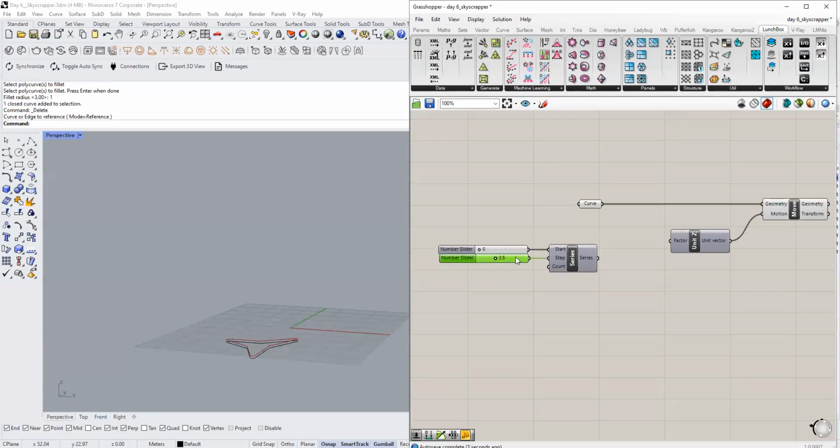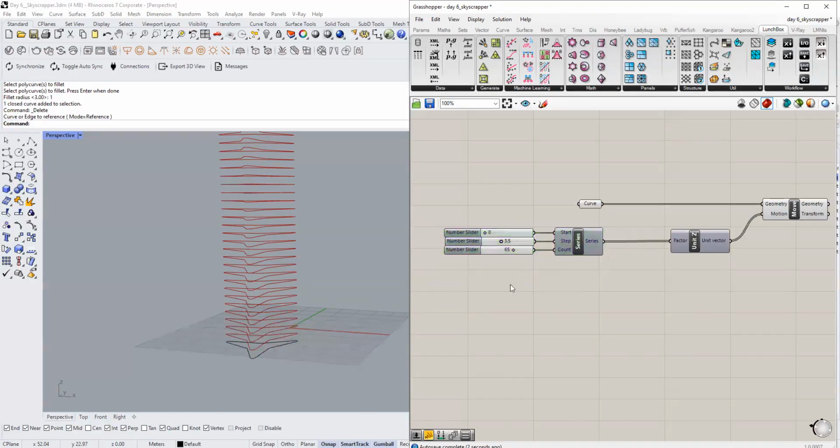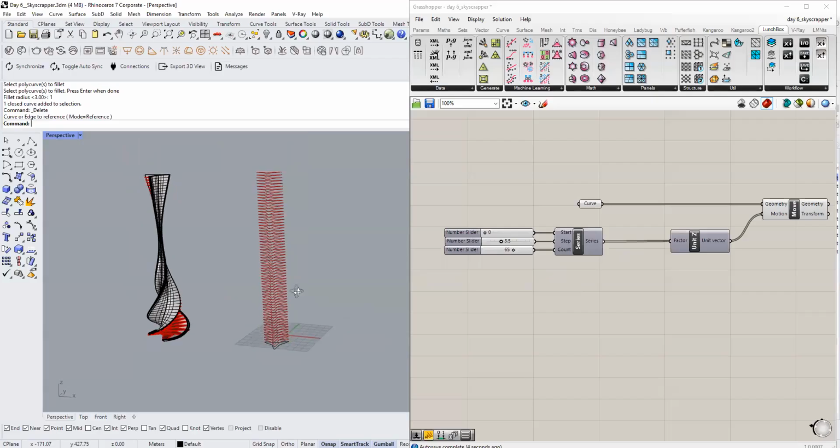And finally, the count, what would it indicate here? Any number. I mean, any number, yes, but in this context, what do you think the number indicates in terms of moving the factor? The number of floor plates you want to create the height. Exactly, the total number of floor plates I would like to have. I would like to have maybe 65 floor plates. Let's give that here. The resultant series goes into the factor, and you can see automatically I get multiple floor plates like this.